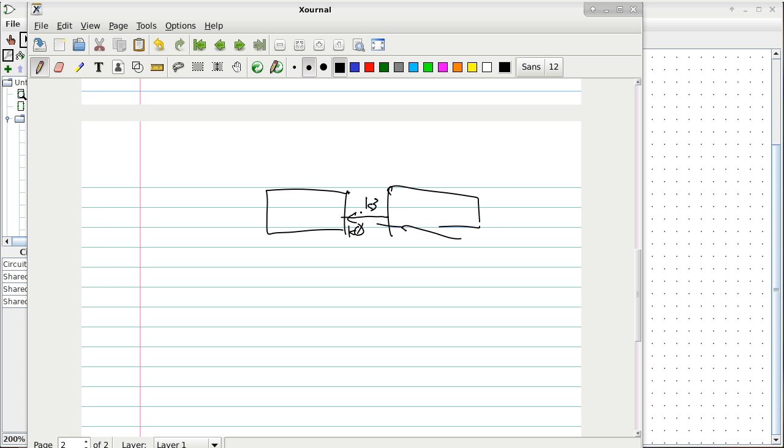It's like, do I really need a single clock adder, or can I live with a 2-clock adder? And if in the application the silicon cost is more than what it's worth, then you go, we can just lose a little bit of time, but we reduce the complexity of silicon. So is that kind of answering the question? Okay, very good.